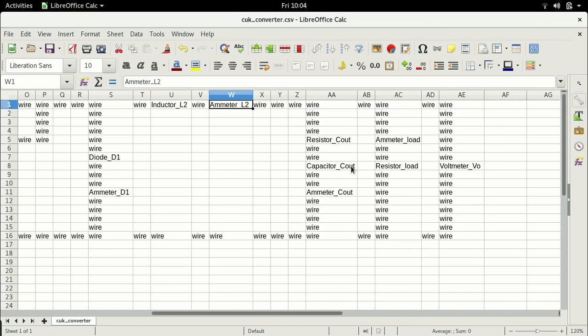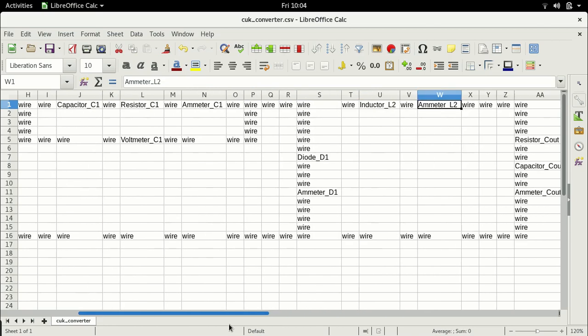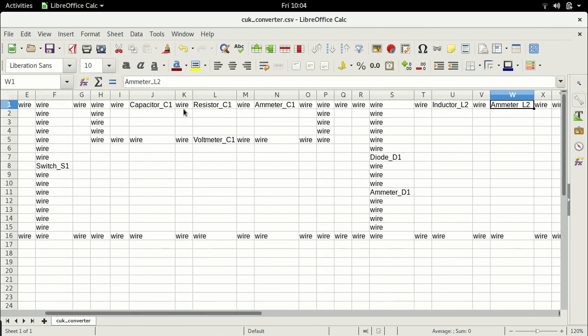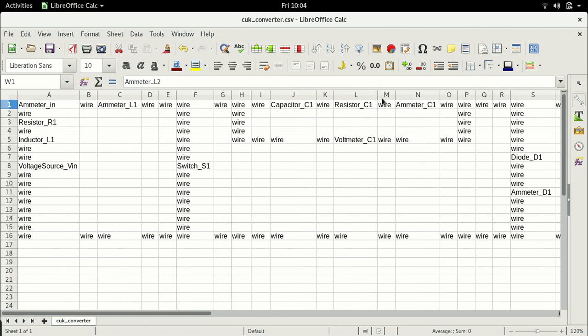So this forms the output bridge, or you can say the output bus. So this needs to be large. It needs to be way above, maybe 500 to 1000 microfarad. But this capacitor C1 need not be that big, but still it has to be large. The reason is, this is actually an energy decoupling capacitor. This is not a filter capacitor. So this does take a significant amount of energy from the input and transfers it to the output. So we do need some amount of size here.